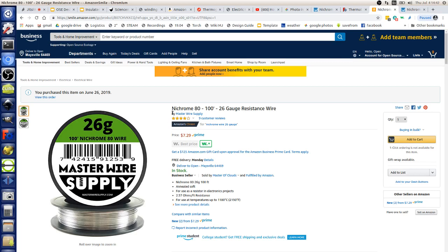I took the on-off duty cycles, basically how long the heater is on when you have an insulated bed versus the back being open, using our DIY heater. And I found that at 100 Celsius we're using 30% less energy, and at 177, so I actually took a look at the max of this, we're using 40% less energy to keep the bed hot.